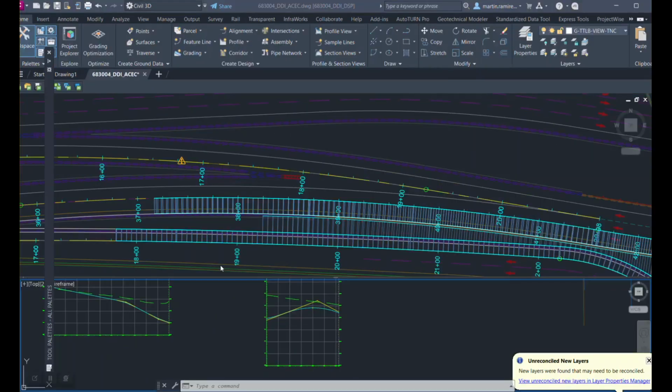So that has been my introduction to Subassembly Composer and how you can use it to derive some of the design elements that you might need on a project. In our situation, it was a wall. There's a lot of things you can do with Subassembly Composer, and hopefully now that you know how to set input parameters, targets, how to create points, auxiliary points, also take some of the workflows that I used, which was creating auxiliary points first, then having decisions in order to know when to make actual points, is useful.